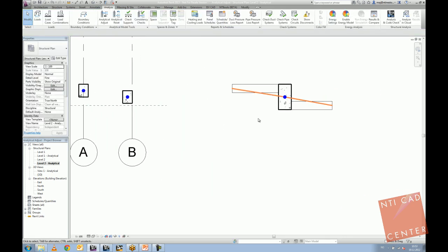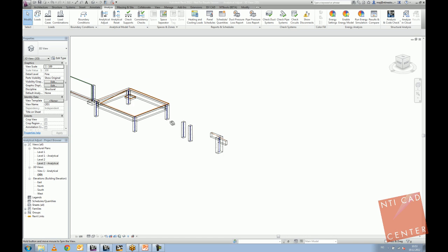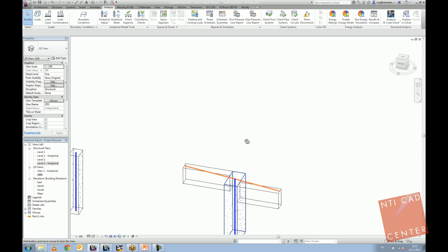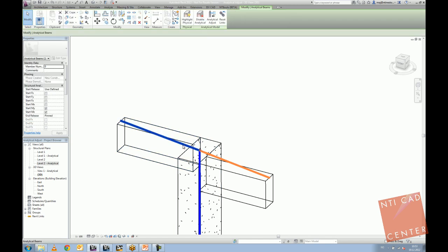One of the last examples here is actually this one. In some cases you might have something like that. Beams, elements, and then again how they should actually join. Maybe you want to have additional moment here. So by selecting the analytical line, you have two options. One of the options would be saying that this analytical link is yes.